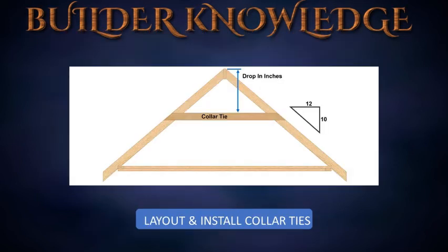Layout and install collar ties. One method of strengthening a roof is to install collar ties at every second or third pair of rafters. Collar ties should be installed in the upper third area of the attic space and are fastened at each end with 4 8D common nails. Divide the amount of drop of the tie in inches by the unit of rise of the common rafter.